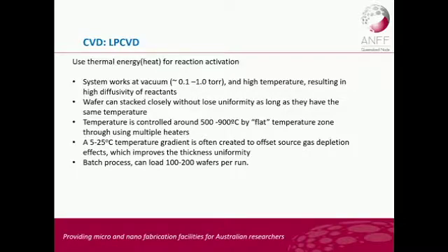First, I will talk about the LPCVD system. LPCVD means low pressure CVD method. So you use thermal energy, that means a heater, to activate the gases. Usually the process is carried out at 0.1 to 1 torr pressure at high temperature.